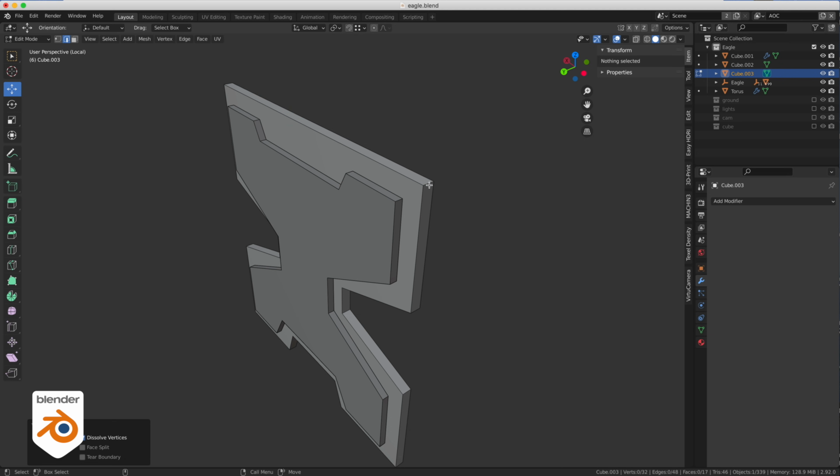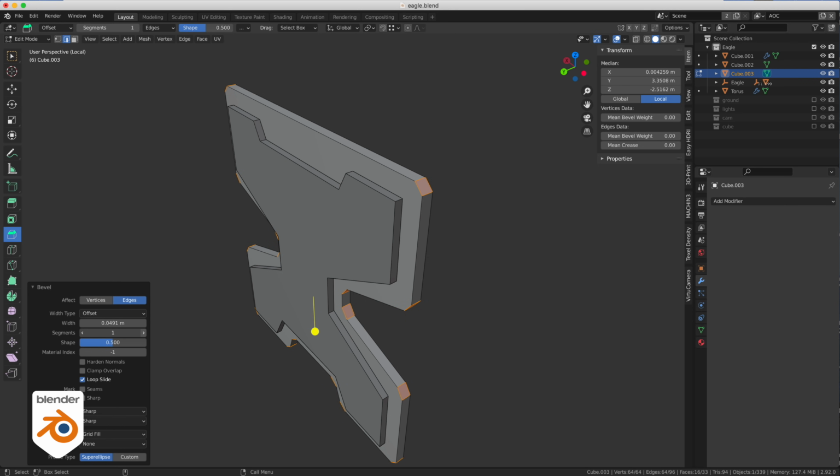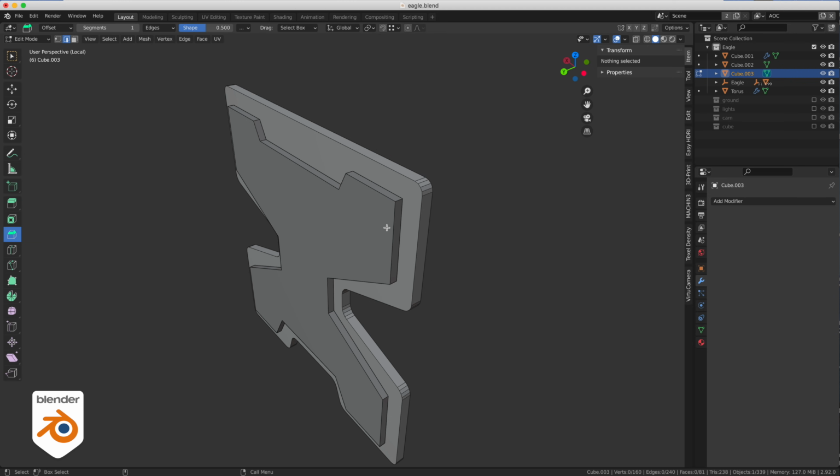At this point, I want to bevel the corners like we did before, so I use my hotkey to select the entire edge ring. Remember we talked about this before. Now it's done, I can just bevel it a little bit, so I'm going to just bevel it like this and put 4 divisions. Always use an even number, not an odd number. There's a reason for that, but that's in advanced modeling. Just trust me on this one, okay?